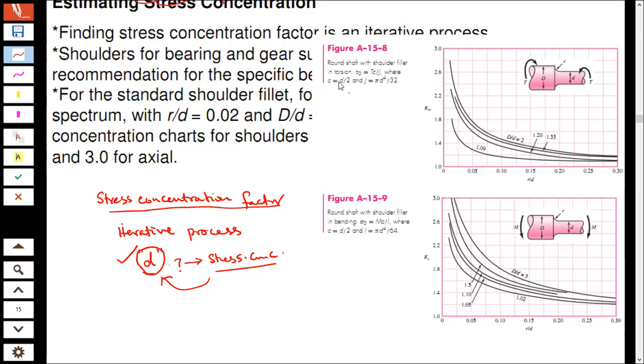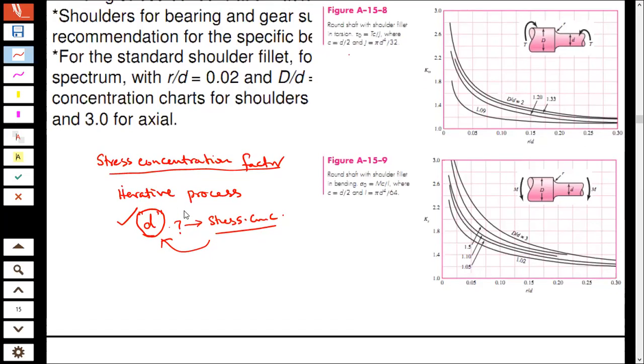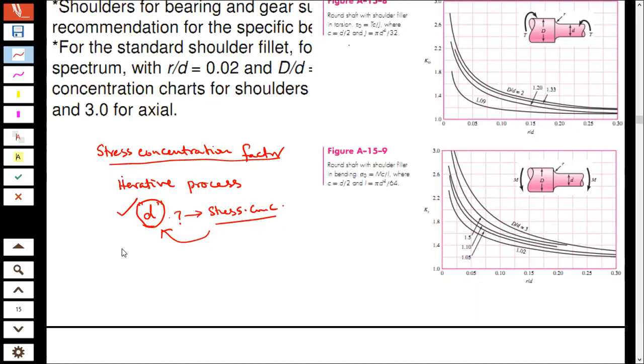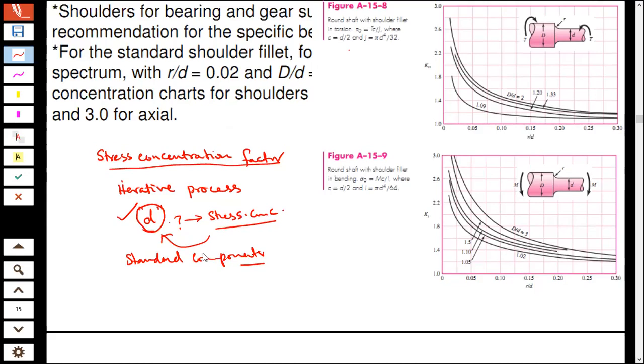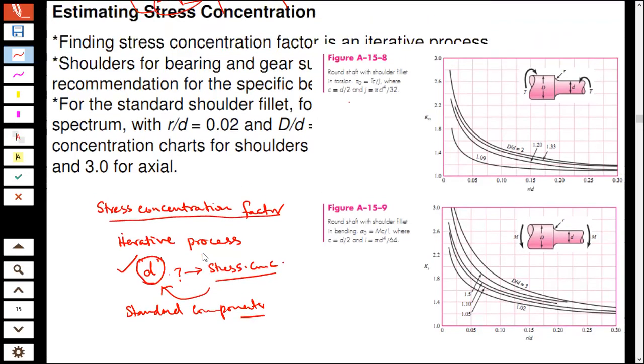Okay? Now, the good thing is that when we design shafts, we use very standard components. So even if we don't know the diameter of the shaft, we can still come up with the stress concentration factor initially. Okay?